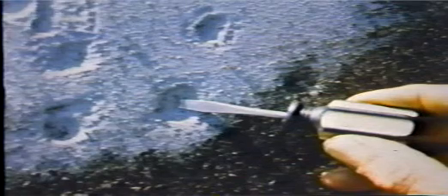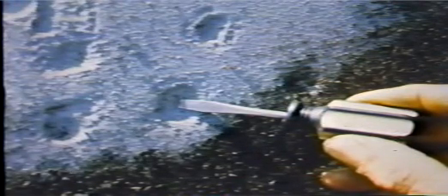Also look for concrete deterioration, including disintegration, spalling, slivers or slabs of concrete breaking away from the surface, pop-outs, small indentations left when portions of concrete break away from the surface, pitting, tiny cavities in the concrete, and scaling, flaking or peeling of the concrete or mortar.